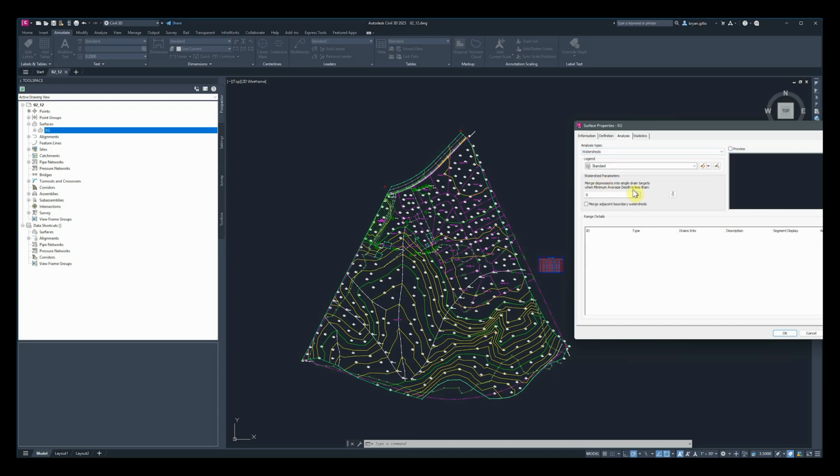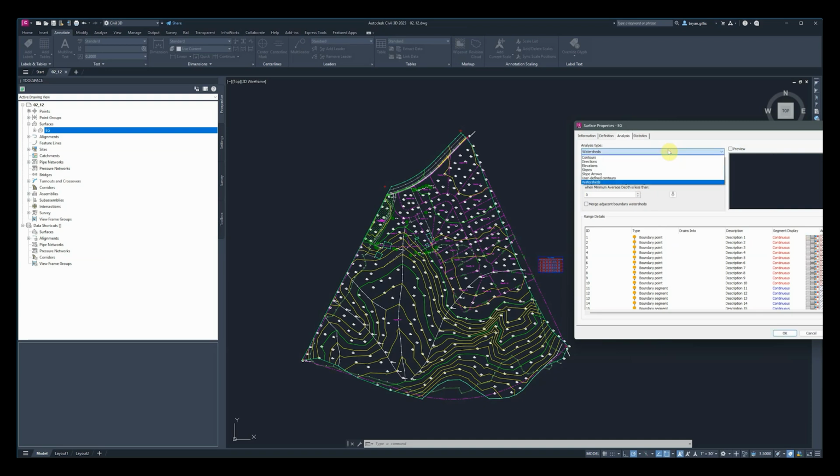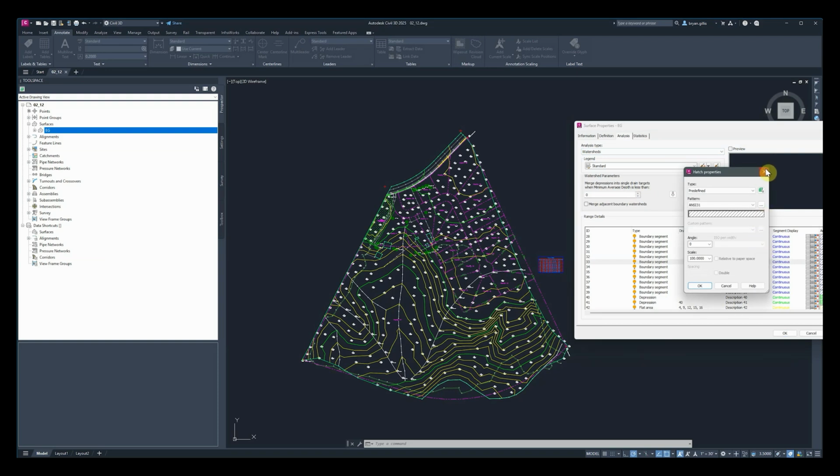Go to our watersheds. Go ahead and default that up to 8 as well. Excuse me, we can't adjust this yet. Just run it as its default of 0. And then here we see watersheds, unlike our lines or our points, we're actually looking at areas. So we're going to have options to apply different hatches and hatch colors as well to each of our ranges that are going to be generated for us.